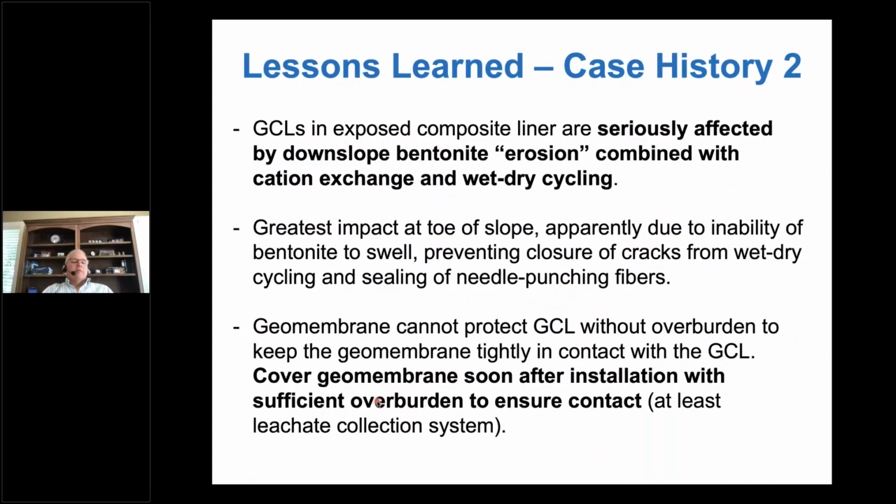So what are the lessons learned from this case history? One, GCLs in exposed composite liners are seriously affected by downslope bentonite erosion. We saw one GCL where almost all the bentonite was gone, combined with the effects of cation exchange and wet dry cycling.